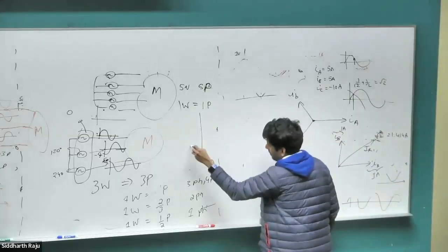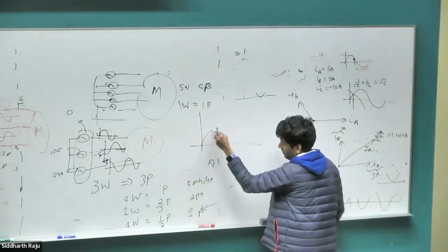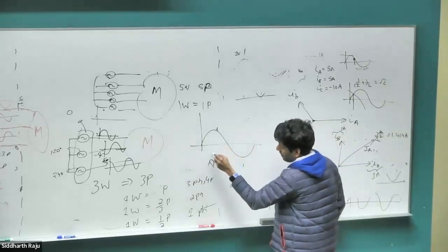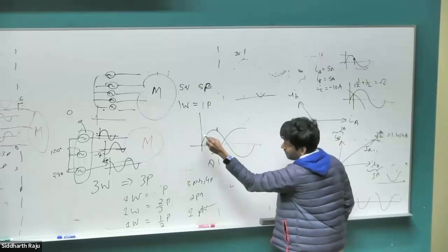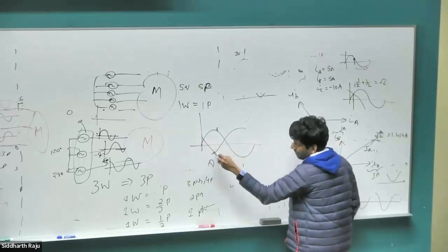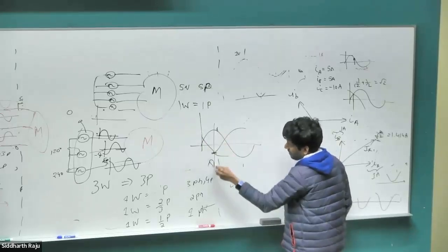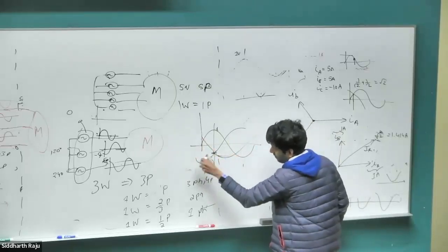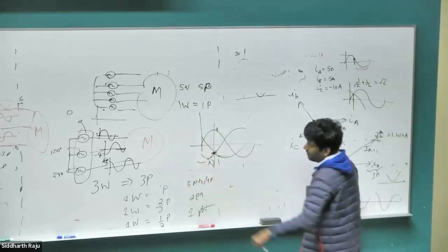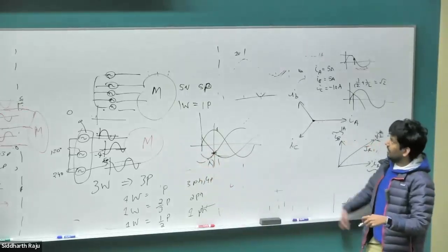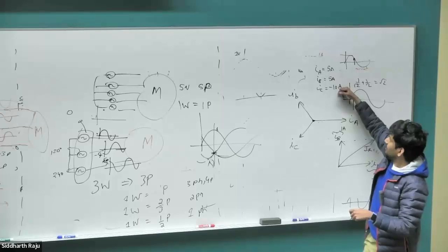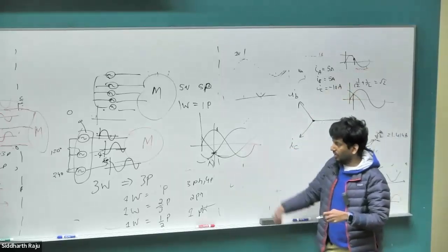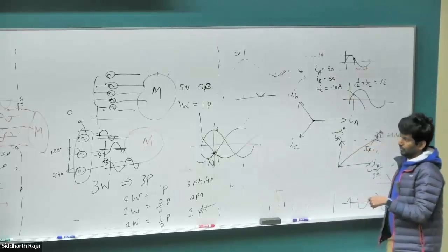Because when you look at your three-phase currents and voltages, if this is one of them and the other two, wherever the other two intersect, the third one would be at its peak. Right, so if the other two phases are given as equal, then the third one is representing the peak. Okay? So that's how the three-phase works, because of the 120-degree phase shifts. So that's an easy way to determine that.